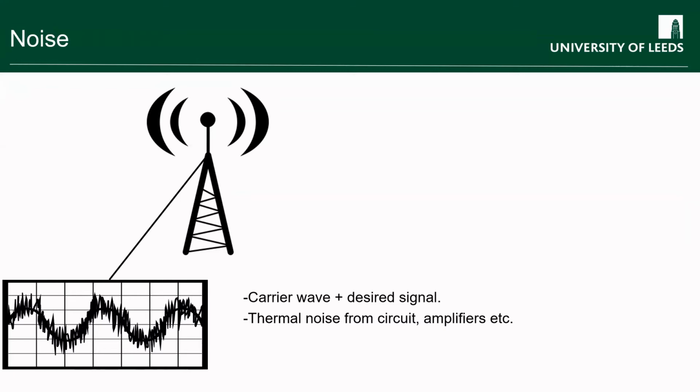And these additional signals, even if you don't have anything else going on, come from thermal noise that happens in the circuit, in the amplifiers. So it's noise being introduced in the receiver as electrical noise, which you're then hearing, and that's characterized by a background hiss that appears at all frequencies. We'll explore a bit later why we get that.